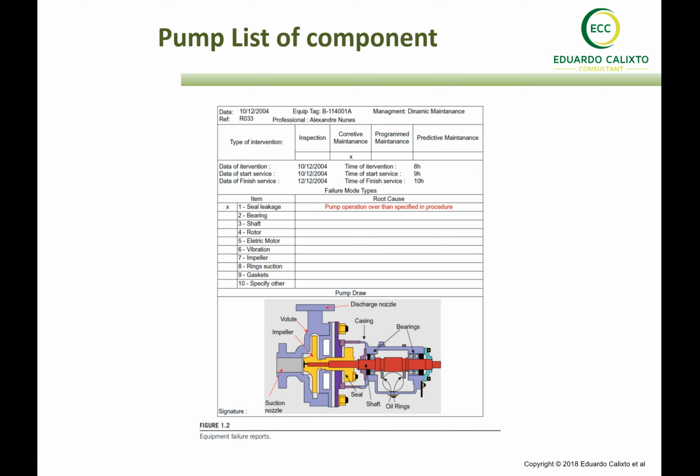And these files in some cases are not an electronic source, they are on paper. It's not a big issue as well. We need to sit there and look at this equipment's history of the failures that happened, and the technicians and operators that will be part of the RCM workshop need to bring such information in order to give some inputs and also justify their recommendations concerning maintenance tasks to the group.